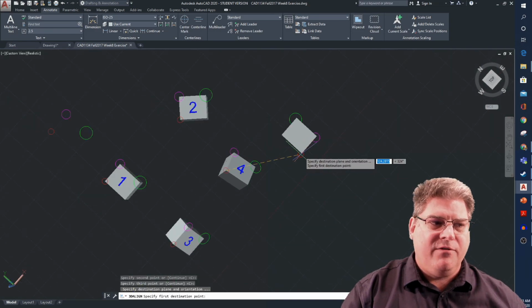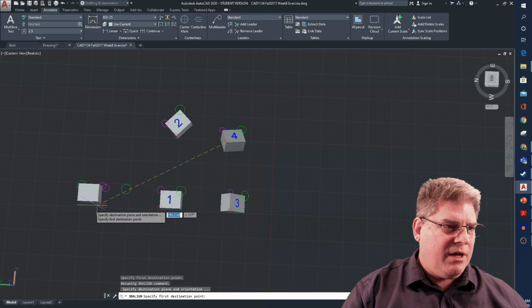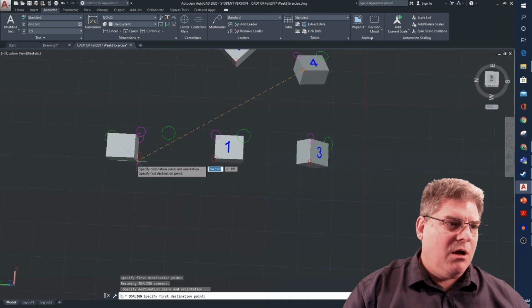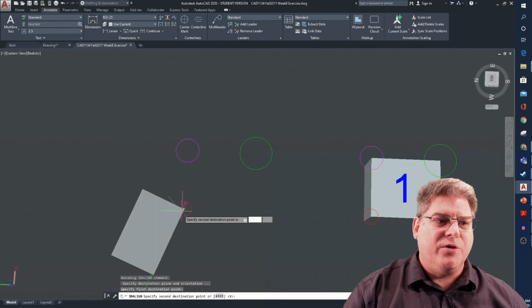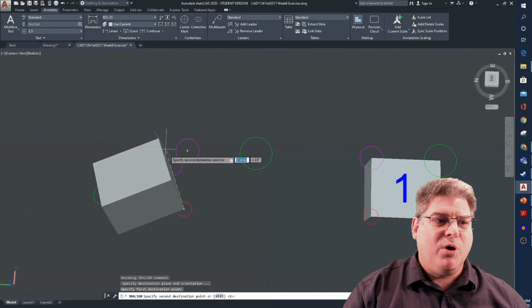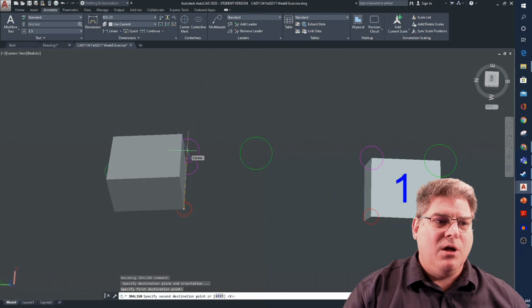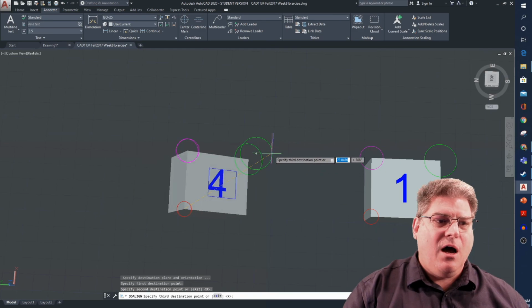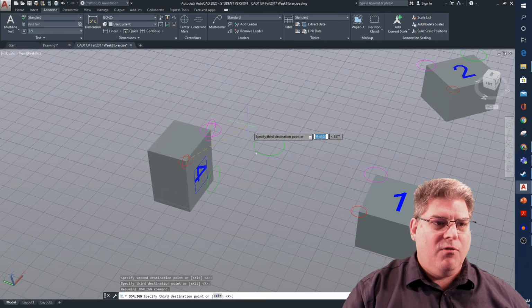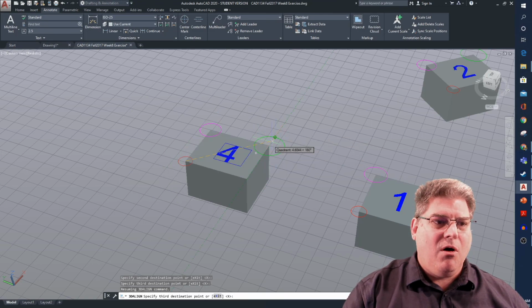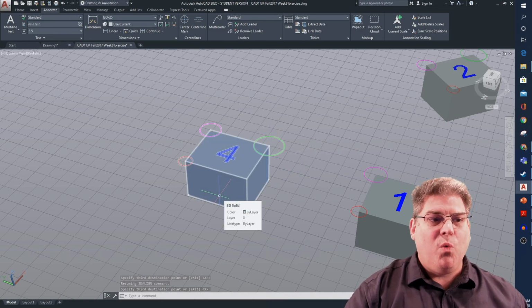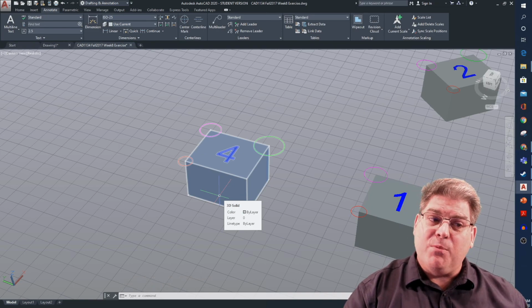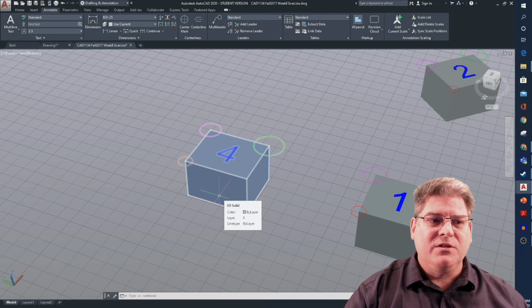And you'll notice that I can kind of drag the part around with me. And so in this case, because I have something nice and visible, like that red circle, I can line up the red circle to the red circle. And now it's trying to get the purple or the magenta to line up. And so here we go, magenta to magenta. And then finally, I can bring the circle around for the green till it lines up on the center point as well. And insta presto, we have a perfectly aligned part. If your part ends up inside out, upside down, backwards, then you know that you've picked the order incorrectly.